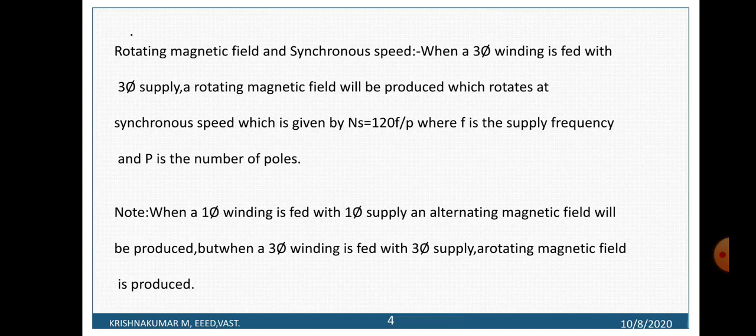Then a magnetic field is developed in the stator, which is rotating at a synchronous speed. The magnetic field is rotating at a synchronous speed, which is given by Ns equal to 120 F by P, where F is the supply frequency and P is the number of poles.